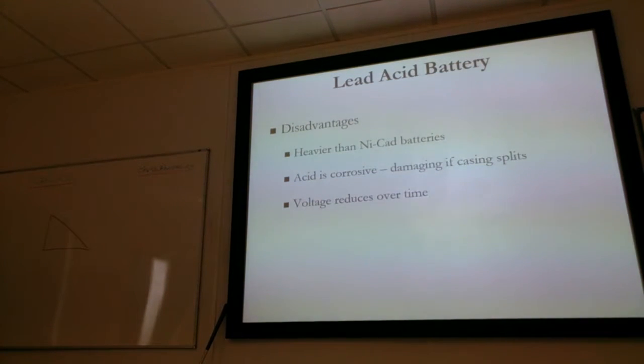The voltage that the battery is capable of storing reduces over time, and it seems to be seasonal, doesn't it? Our batteries only ever fail when it's midwinter. They've got a slow charge rate. Safe rate of charge is something like 8 to 10 hours to charge a battery from fully discharged to fully charged.